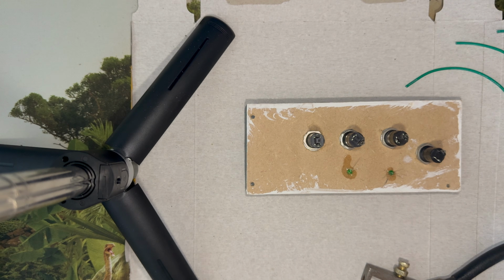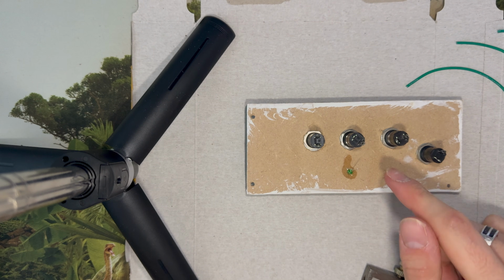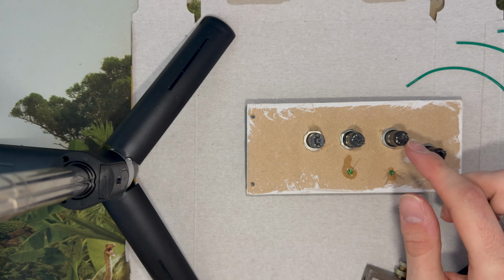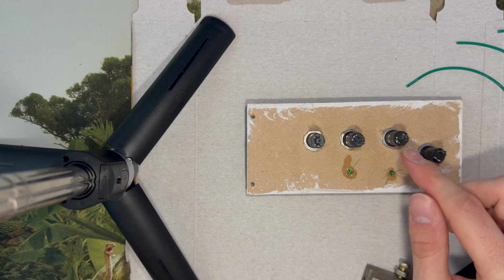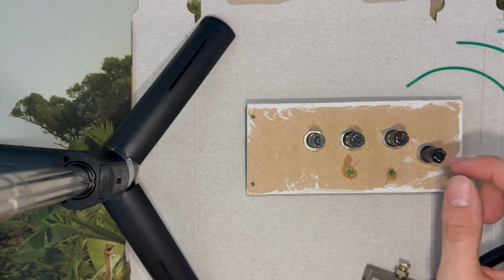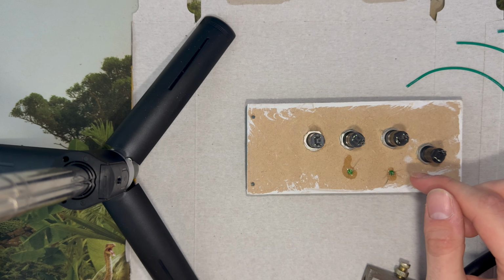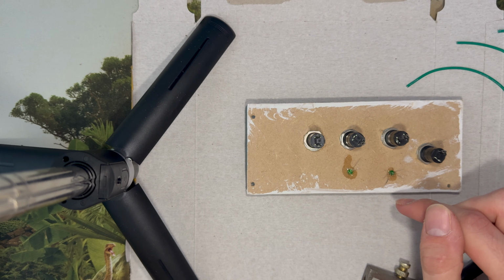Now I'm going to start the wiring process for this panel. As you can see, each of the components here, they have two prongs coming off them. We have a positive and a negative. On the buttons, it's quite simple. You can use either one for either. The LEDs, however, it's just the longer wire coming off is the positive and the short wire coming off is the negative. So we're going to focus mainly on the negative side for the moment.